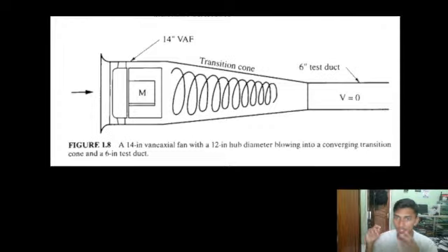And this setup of course was not in accordance with the Air Movement and Control Association, or AMCA, test code, which required that the test duct area be within 5% of the fan outlet area. A better test would have used a nozzle chamber instead of a test duct, but in 1949, very few companies had a nozzle chamber.